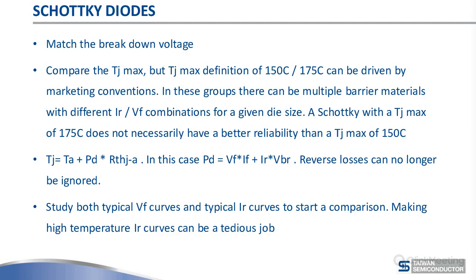And you also have to watch out because making high temperature leakage curves is a tedious job. Suppliers have thousands of datasheets, and maybe not all Schottky datasheet high temperature leakage graphs in the industry are correct. So you're probably going to have to measure it yourself in your own circuit to make sure that you're comparing apples to apples in your application.